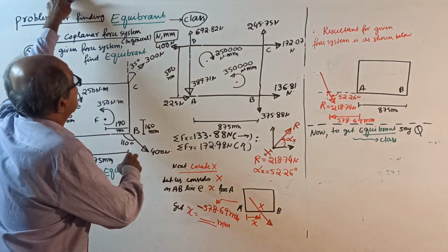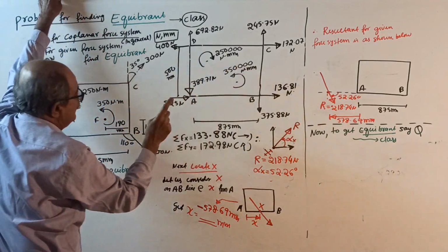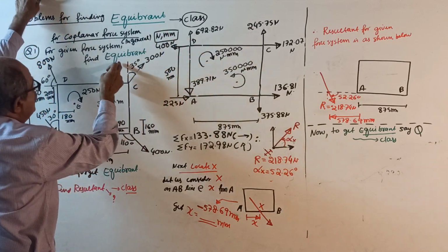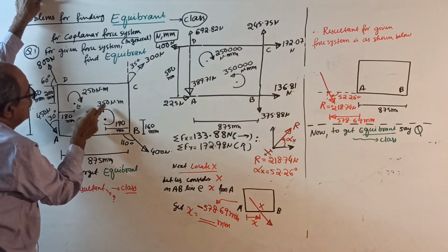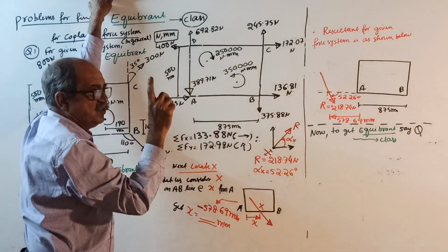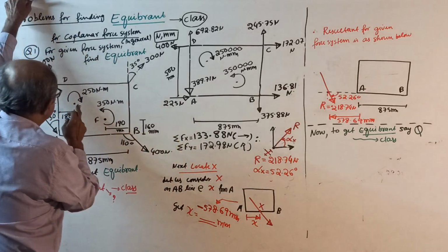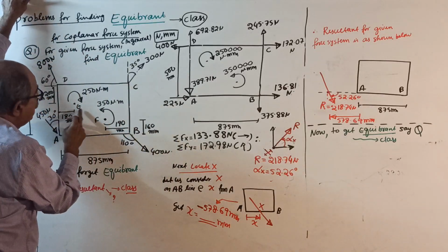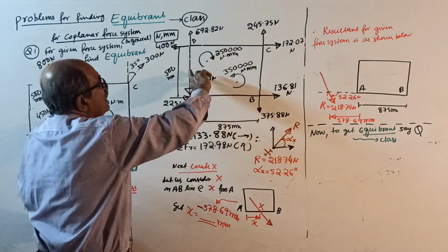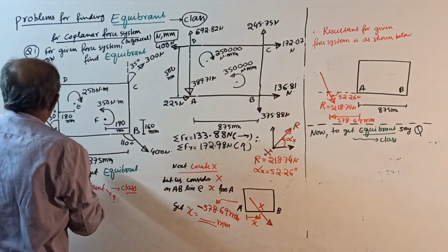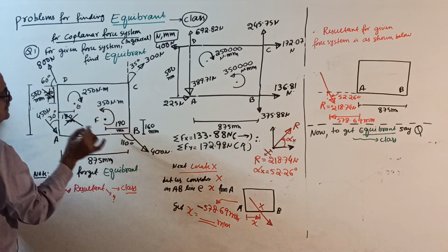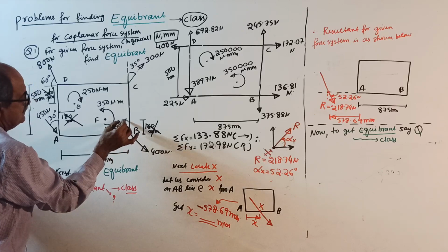Okay, start. Resolution I had done. Very important, we will solve in newtons and millimeters. All forces are in newtons, but the two couples are given in newton meters. You have to convert them to newton millimeters. I already told it. They also told where the couple point is here. This is not required, because when you take moment about any point, the couple's position is not needed. You can make a note: this distance is waste, this is useless, this is also useless.